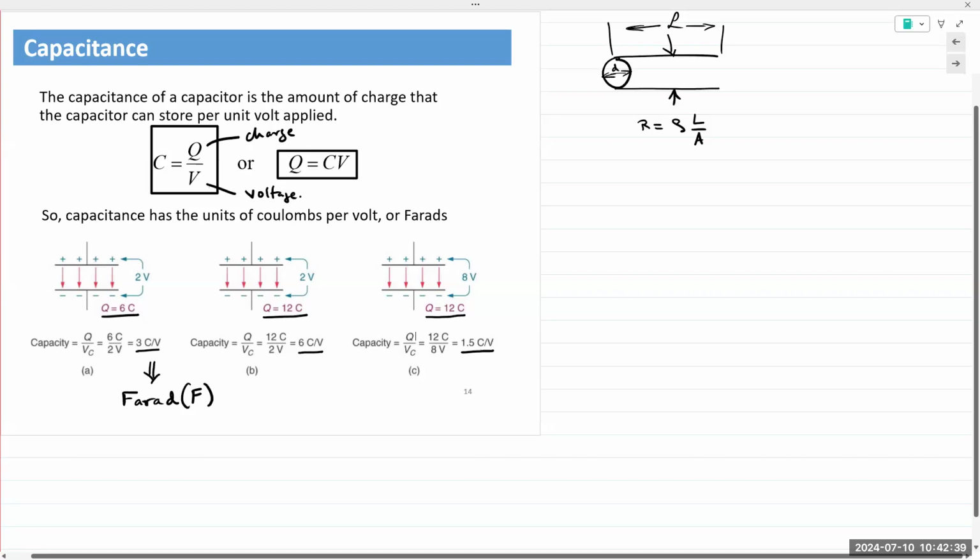It's 350 volts because the physical components inside the capacitor have to be able to handle all of that voltage. If it was the same 1,800 microfarad capacitor with, let's say, 10 volts, it would be far smaller. It would be probably about this size.